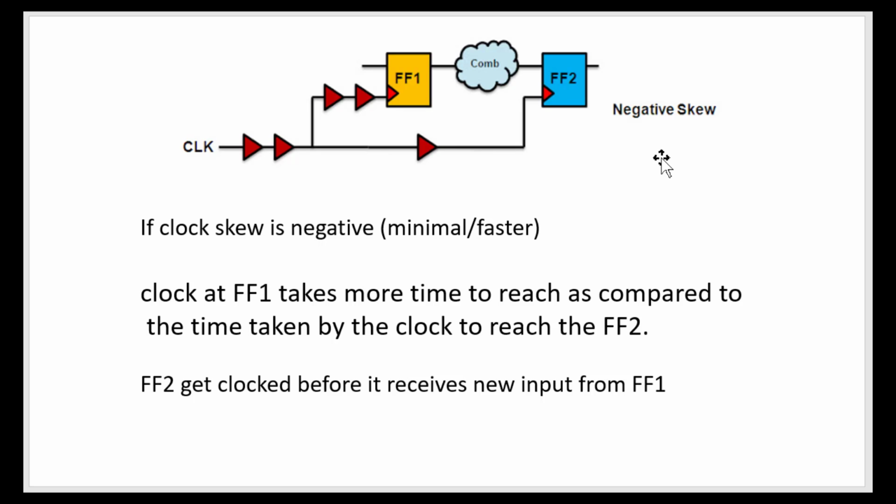So you have to make sure that each flip flop responds the moment the previous one produces output to the next flip flop. You have to add extra gates or extra delay wherever it is required so that all the flip flops take the appropriate output from the previous flip flops and produce reliable output. That's why clock skew is very, very important in designing a digital circuit when you have more than one flip flop.